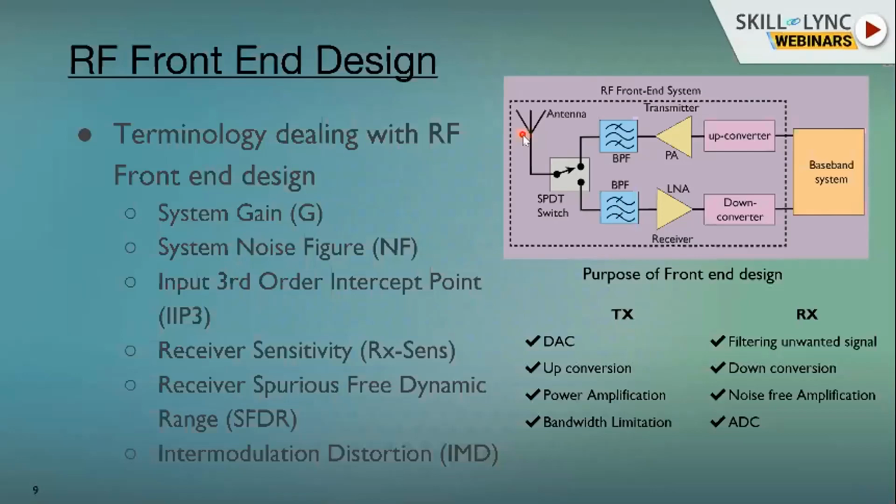It's a kind of folded antenna, and it is working from 800 megahertz up to 5 gigahertz or 6 gigahertz. It covers all the frequencies from GSM, LTE, GPS, Bluetooth, and Wi-Fi together. So that is one of the challenges: how do you design this antenna and accommodate it inside your mobile phone or notepad or iPad or anywhere? When I mentioned IoT devices, there it is the biggest challenge.